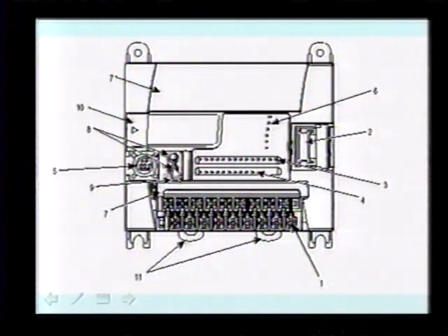You've got 2 potentiometers here. You can actually use these potentiometers for field adjustments. There's a small button right here that, if pressed, will change the communications of this port to the default communications, which is DF1. The neat thing about these MicroLogix units is they can turn port 5, or that main port, into a Modbus communication port.